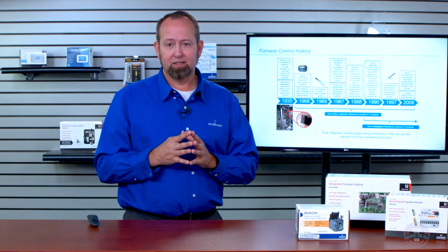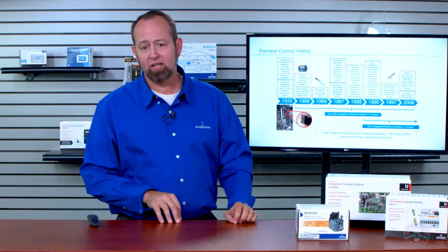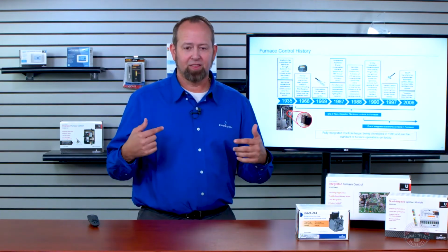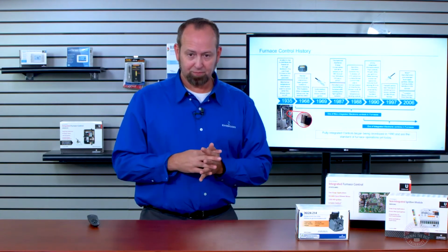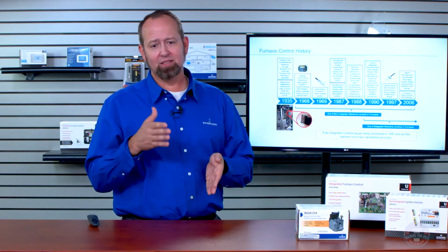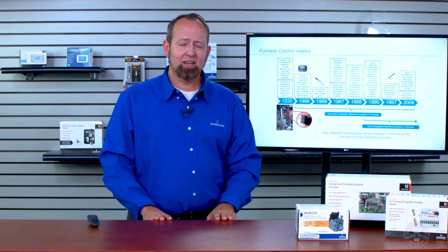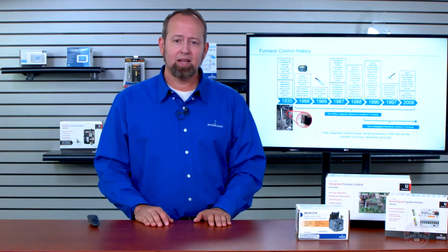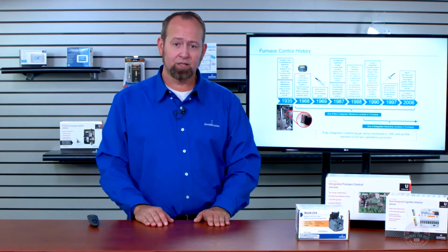Several years later, the 120-volt silicon nitride igniters came out, and with that, it was determined that you could have that full voltage. You didn't have to drop the voltage. Now, a word on 80 versus 120. I had a homeowner several years ago that had a technician come out a couple times a year and replace the igniter in their furnace.